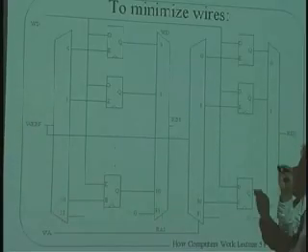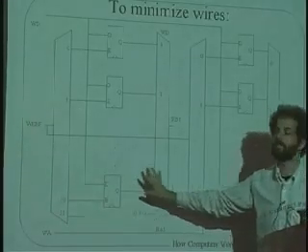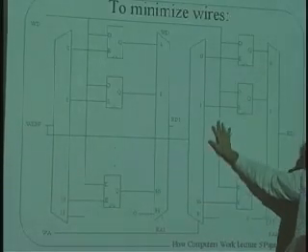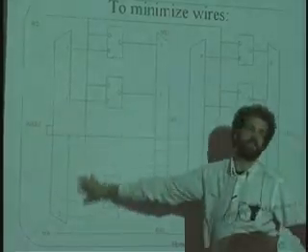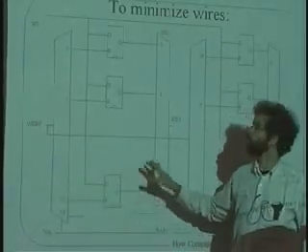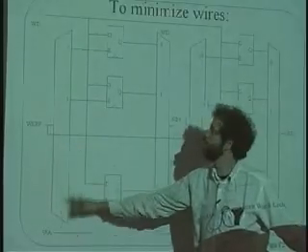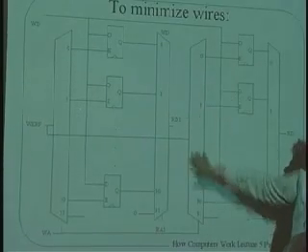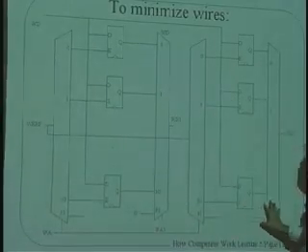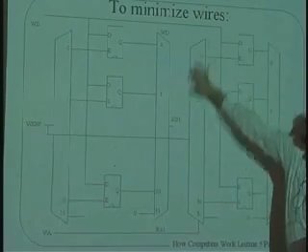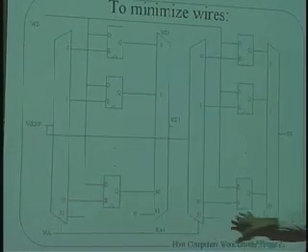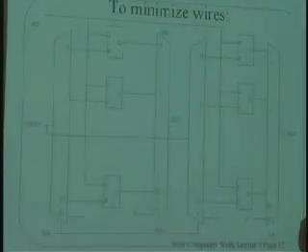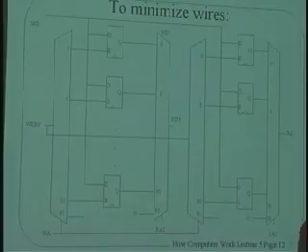Instead of having the same bits from all of these registers go to two multiplexers, what architects in those days did is that they duplicated the register file twice. In other words, this register file over here on the right is exactly the same as this register file over here on the left. Each of the register files has one write port, just like we had before, and only one read port. Now this is small enough that we can fit this entire thing on a single chip. And the thing on the left being exactly the same as a second chip. And now when we look at the two halves, how do we keep the two registers in sync with each other?